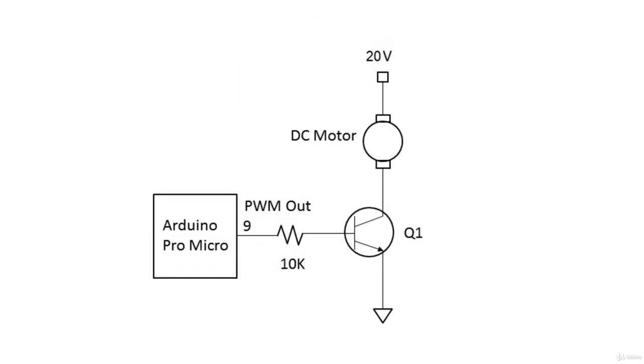So let's create a circuit so that we can drive this DC motor somehow. We need a device or a circuit that can turn on and off this motor using a small electrical signal. For this, we will use an electrical component called a transistor. Using a transistor, we can drive the motor with a high current using a small electrical signal that might come from an integrated circuit, for example. Of course, in the simulator, we will use a switch on the base of the transistor to simulate this behavior.